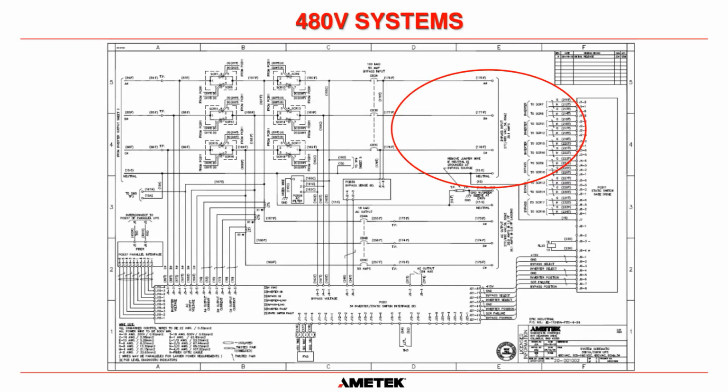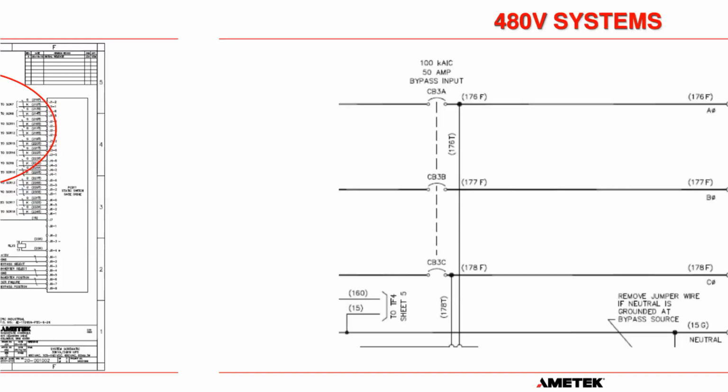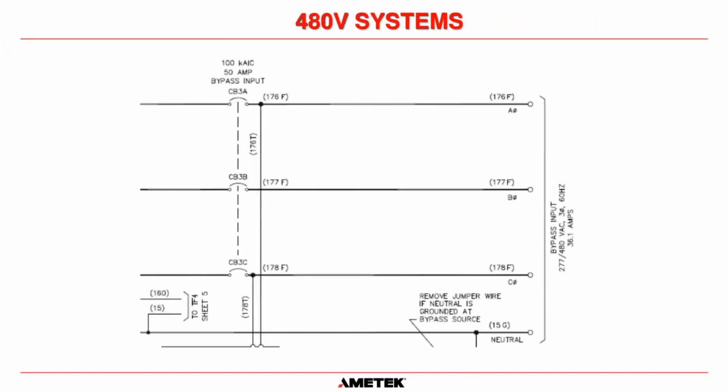So if your system is not running on a high resistance ground system, or you are feeding this from a transformer where you can put a neutral on the secondary of the system, then we have the ability to accept that neutral inside the UPS. And if you do this, then this UPS will work absolutely perfectly without any issues whatsoever. Okay. The big problem occurs, and this has happened on numerous occasions, is when this neutral is not run.